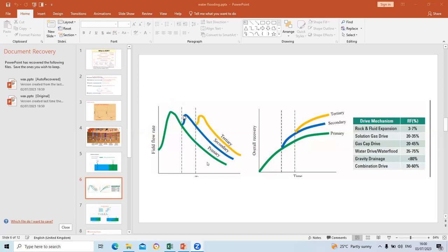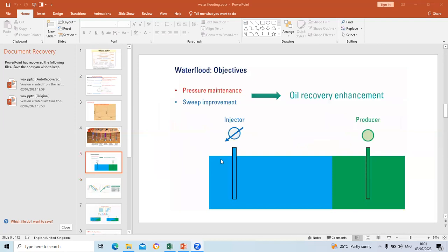But remember that it will increase it up to a point and then it also starts dying down. And when it starts dying down, there is nothing you can do. No matter the amount of water you inject in that reservoir, the oil rate will not increase. Instead, more water is produced. So it's like you're wasting energy, because you inject water and you produce water. So what's the reason for the operation? Because our interest here is to have oil produced at the end of the day.